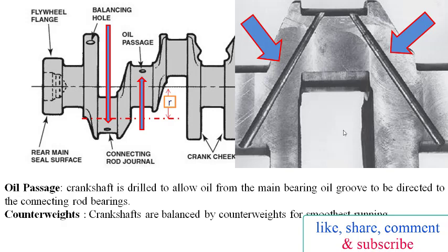When combustion happens, the forces deflect the crankshaft. The deflection occurs in 2 ways: it bends the shaft sideways and twists the shaft in torsion. Harmful crankshaft twisting vibrations are dampened with a torsional vibration damper or harmonic balancer.